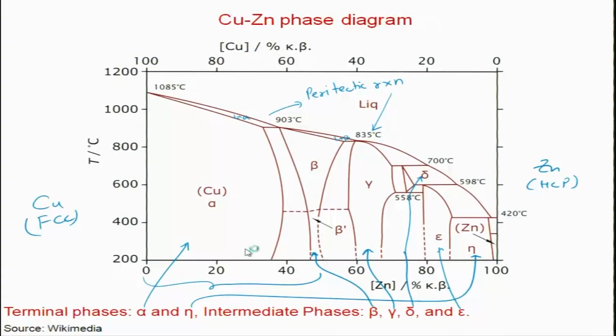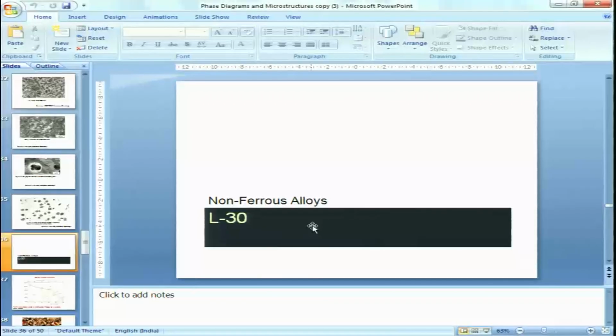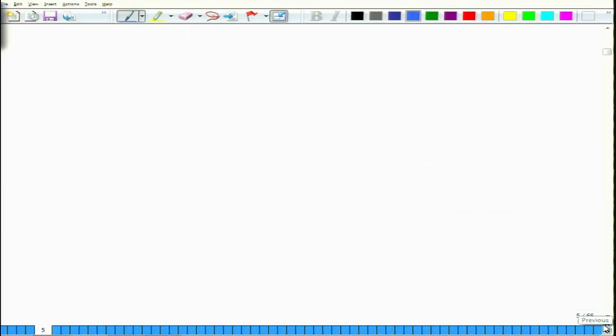so here for example, there is a transformation from beta to beta prime. This is at about 465 degrees centigrade, and this beta phase of copper transforms to beta prime phase, and alpha beta alloys of copper contain this beta prime phase, and this beta prime phase is a hard phase, and which is what provides strength to copper alpha beta alloys. So, the beta phase is cubic based.